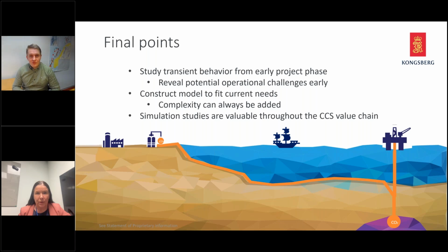Okay, and we'll take the last one here, Sigve. Can the churn flow model in LedaFlow be used for CCUS modeling, considering the inability of K-Spice to model slugs? Yes, it can. They're doing a lot of experiments these days to validate these models in LedaFlow, and the results are coming back thick and fast. It's an exciting area to be a part of at the moment, and again, the next release of LedaFlow will include many of these capabilities.